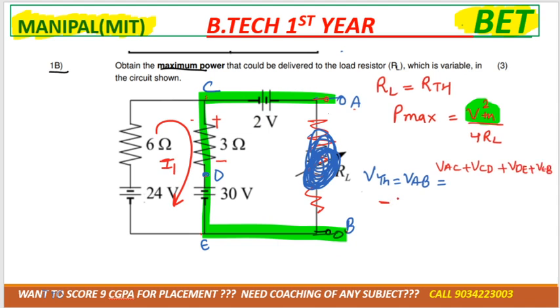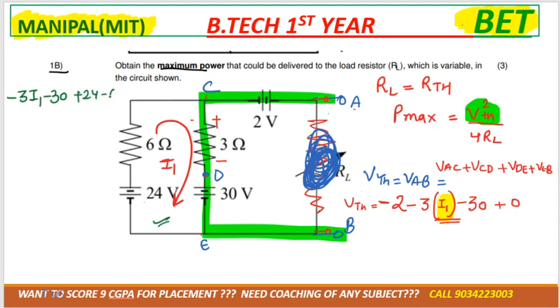A to C, second sign is -2. C to D, second sign is -3 into current. How much is the current? I1 only, because it's a single mesh. D to E, second sign is -30. E to B, no resistance, no battery, so it would be 0. So for getting Vth we need the value of I1, and whenever you need the value of I1 you always have to apply mesh analysis. So we have this single mesh, we can apply mesh analysis over there. That would be -3 I1 minus 30 plus 24 minus 6 I1 is equal to 0, right?